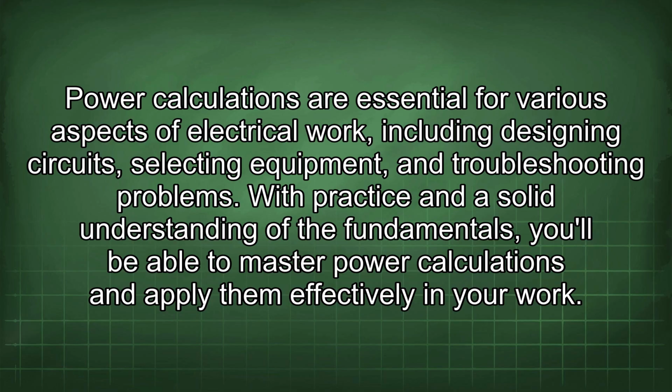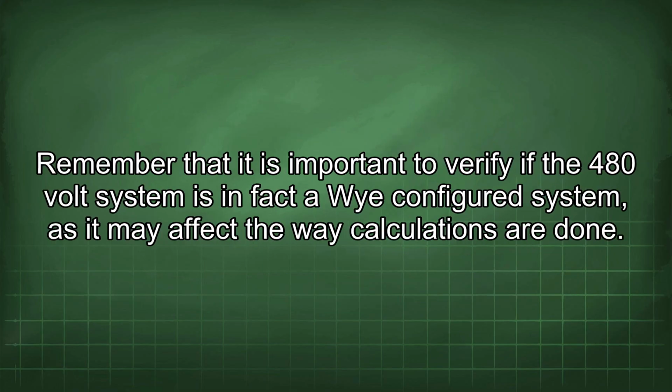Power calculations are essential for various aspects of electrical work, including designing circuits, selecting equipment, and troubleshooting problems. With practice and a solid understanding of the fundamentals, you'll be able to master power calculations and apply them effectively in your work. Remember that it is important to verify if the 480-volt system is in fact a Y-configured system, as it may affect the way calculations are done.